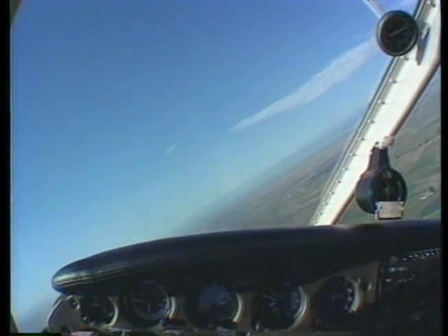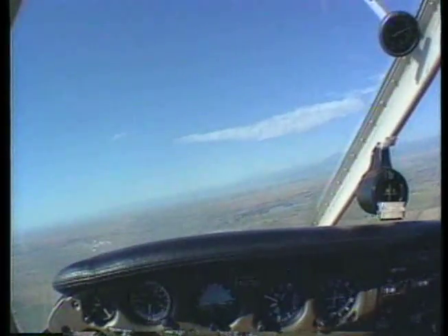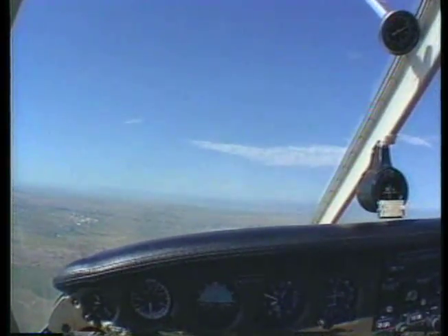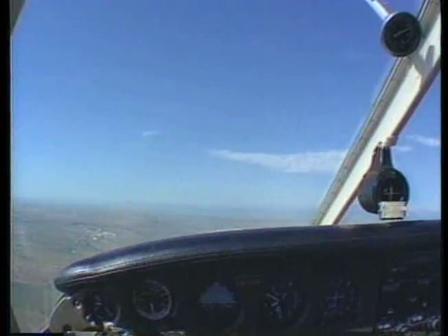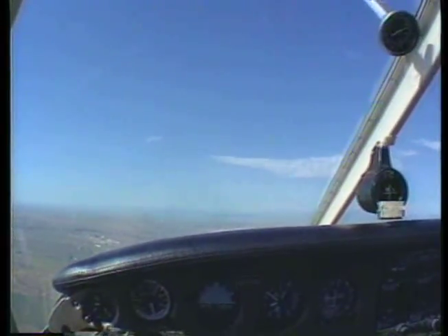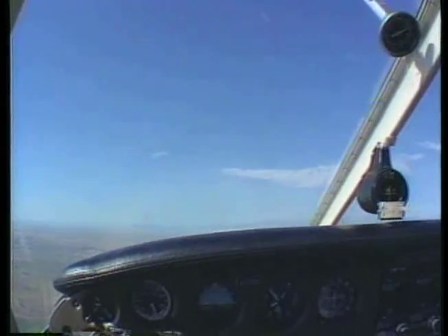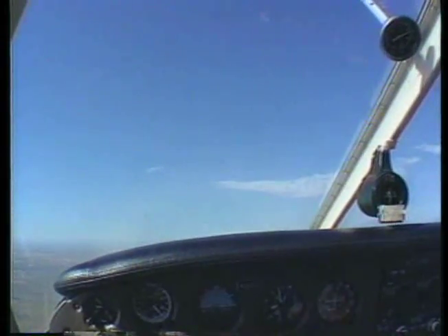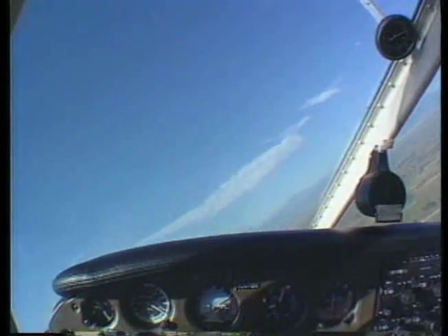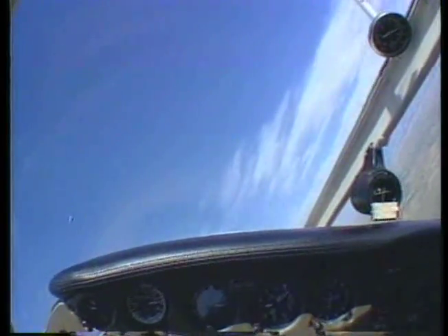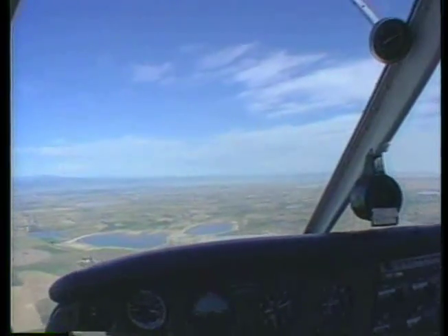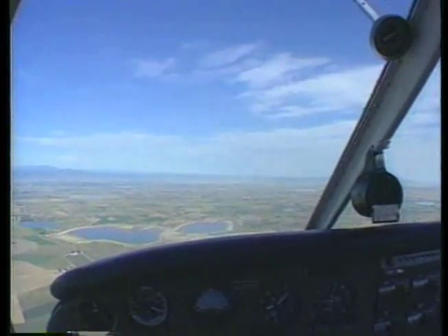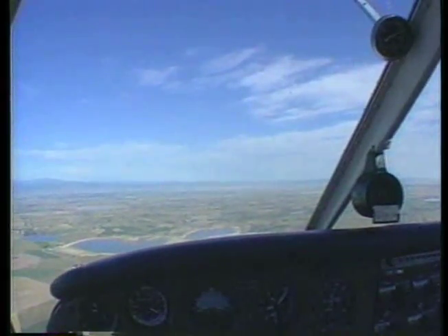Before beginning an accelerated stall, clear the area. Then verify that the airspeed of the airplane is below the published maneuvering speed. This will avoid placing high structural loads on the airplane during the maneuver. Next, roll the airplane into a level bank of approximately 45 degrees and firmly increase back pressure on the control wheel to initiate a stall. Normally, you will recover at the first indication of a stall by releasing back pressure while simultaneously adding full power. Then, use the flight controls to keep the airplane coordinated as you level the wings.